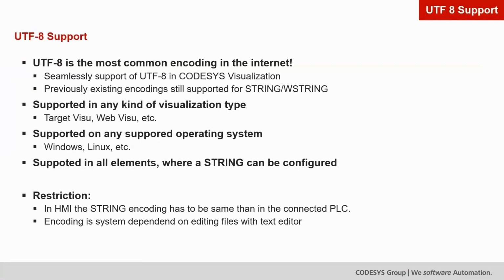We plan to support this most commonly used standard in the internet in the whole CODESYS, as well in the visualization, of course. So with the next version, it is possible to code every string in UTF-8 encoding. Of course, it's not a must to switch over to that encoding. You can still use the previous existing encodings as well. But of course, we recommend to switch over to that common used standard for encoding.